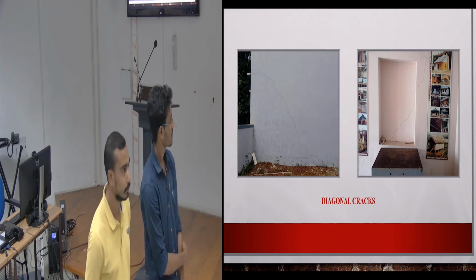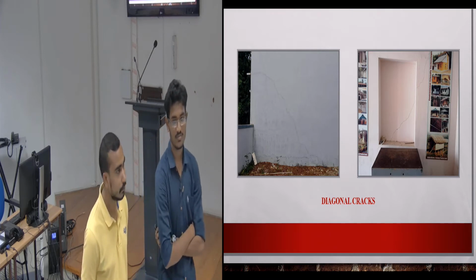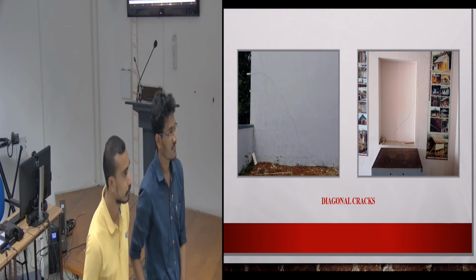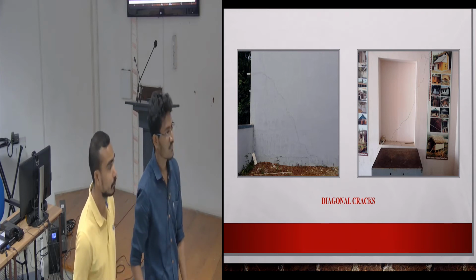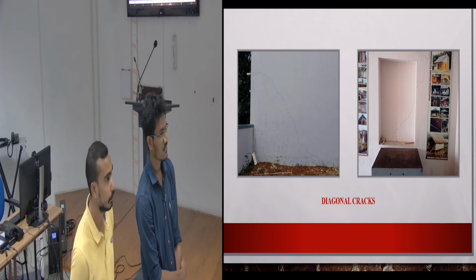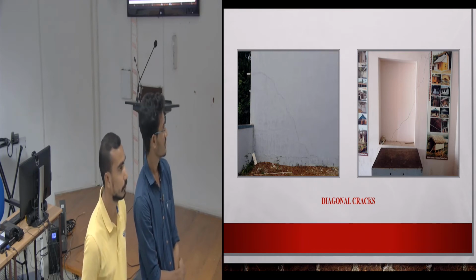Seminar hall in the back, but what is that square? It's a window opening. So that would not have been jointed properly, or they didn't give the provision properly because of the stress concentration. It would have cracked. Have you seen the rear side of this place? No, sir.